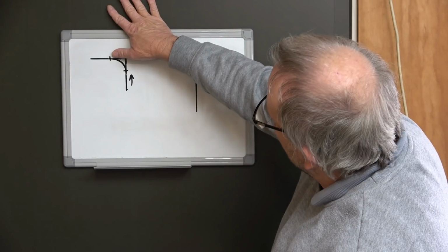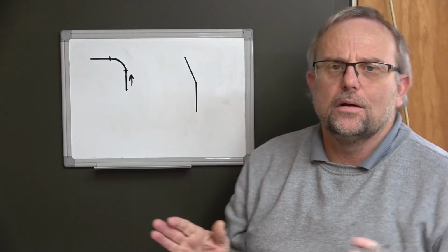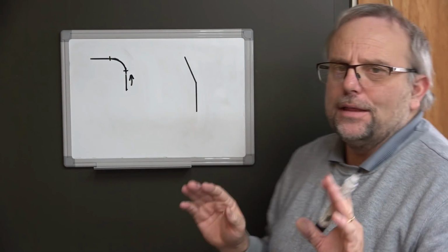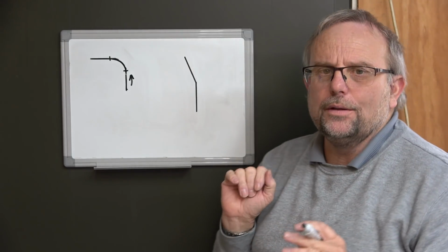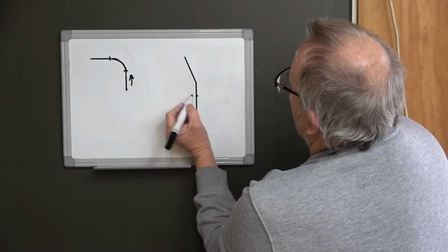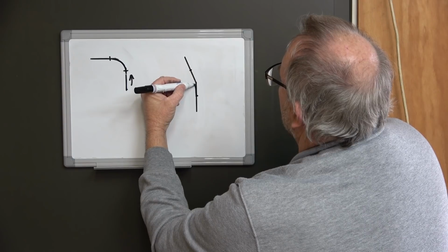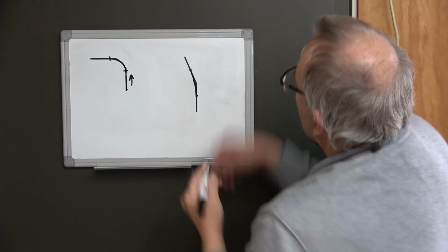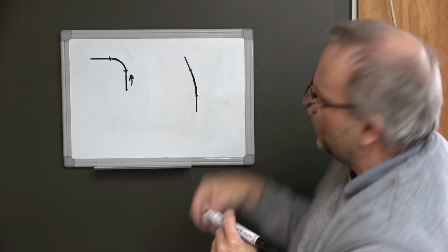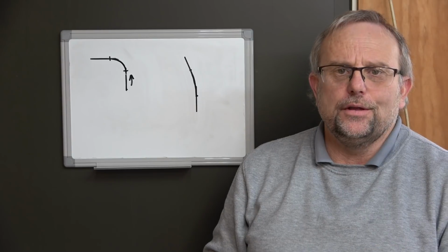So in the case of this 90-degree corner, I lose this much of my corner, and I end up with quite a pronounced curve. Now the error isn't so big on a corner that's got a much shallower angle. So 15 millimeters there and there, I can come up here, and then I can start turning like so. So I only miss just this little bit on the corner. So the shallower my angle, the less error there will be.